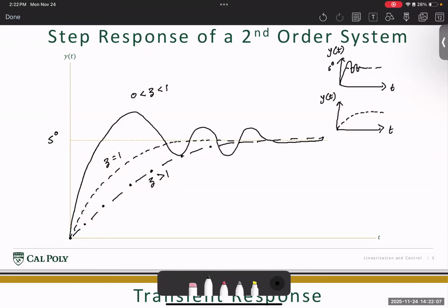The advantage here is that it might settle into 5 degrees much faster, at a time interval of delta t1, while in a passenger aircraft you prioritize comfort, so the time it takes for the system to reach the desired pitch might be longer. This gives control system designers flexibility and control to come up with new designs for the control system.